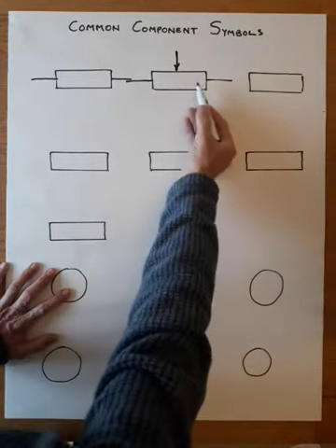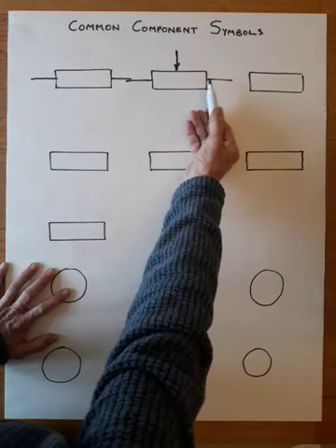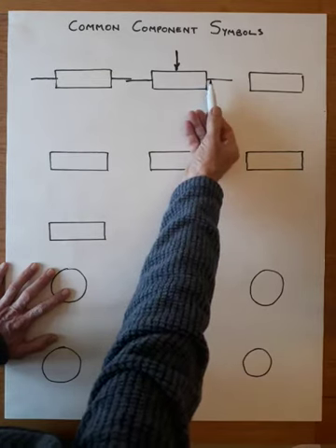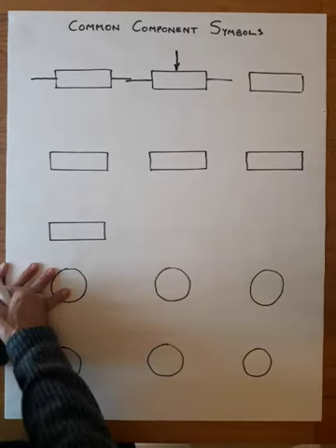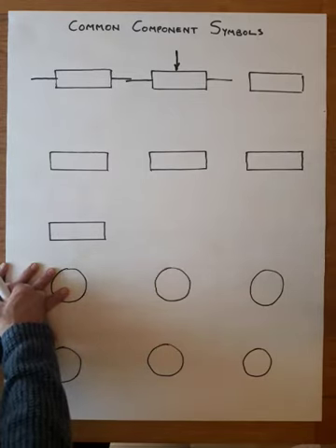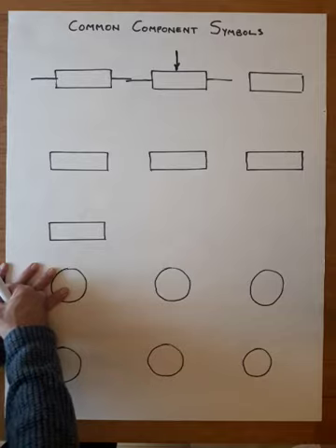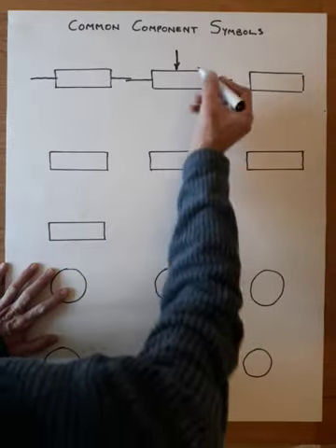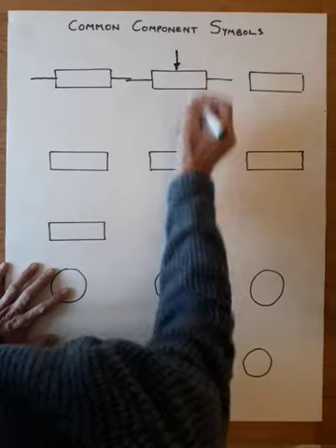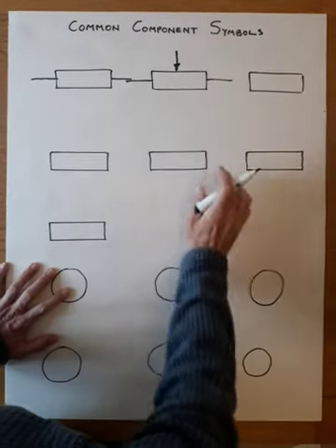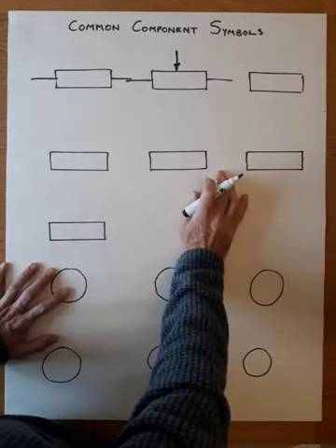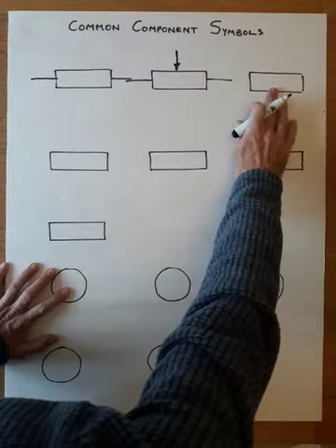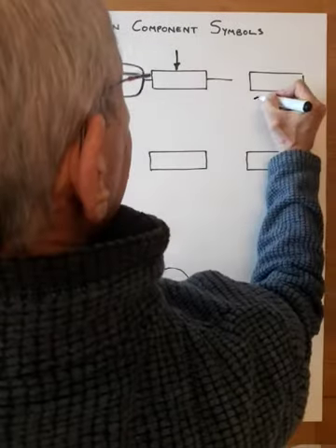so this is now a 3-terminal resistor. This is a potentiometer. The most common place you will find that is like a volume knob on perhaps a stereo system or something similar. So this is called a wiper, this third terminal, and that's the bit that moves inside the resistor. On this symbol,